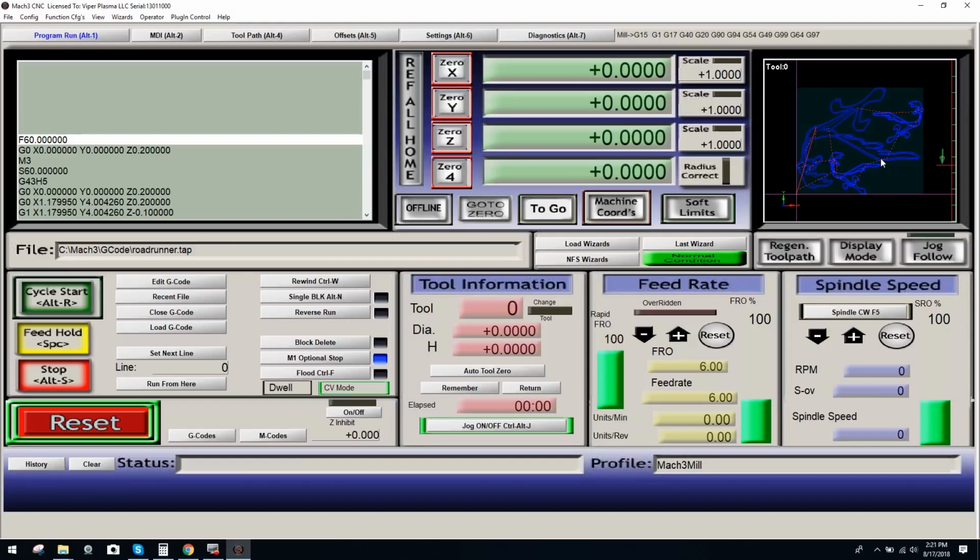You're going to want to jog over to the negative motion, using negative motion I should say, and you want to stop about 1 to 2 inches before naturally hitting the end stop. So I'm just jogging over, I'm exceeding my G code now, and that's why you see that red vertical line there. I'm just arbitrarily jogging, and we'll just keep going, go to 5, so to speak.